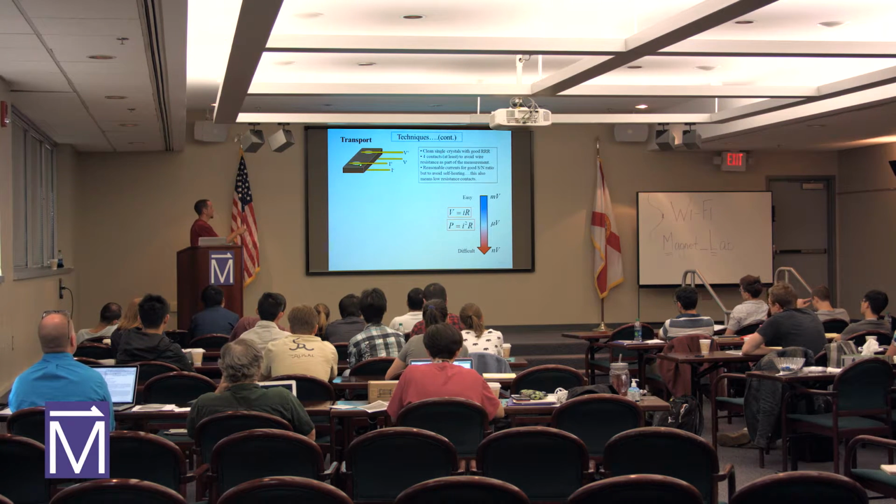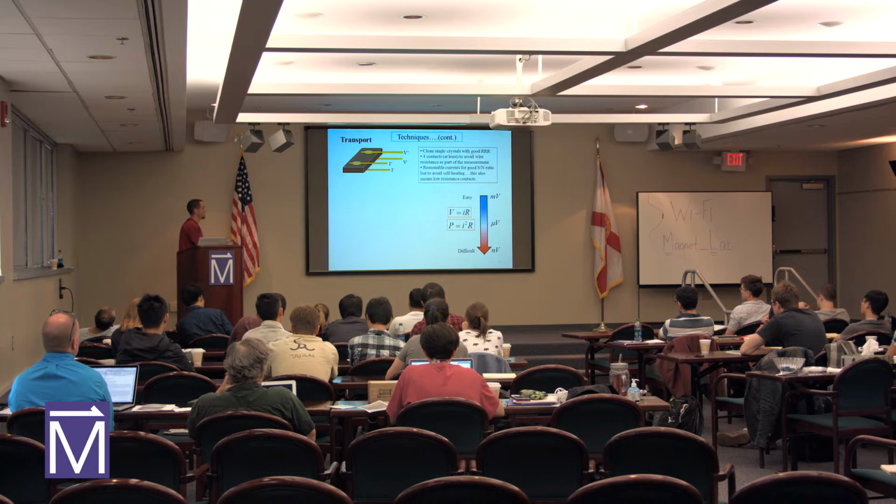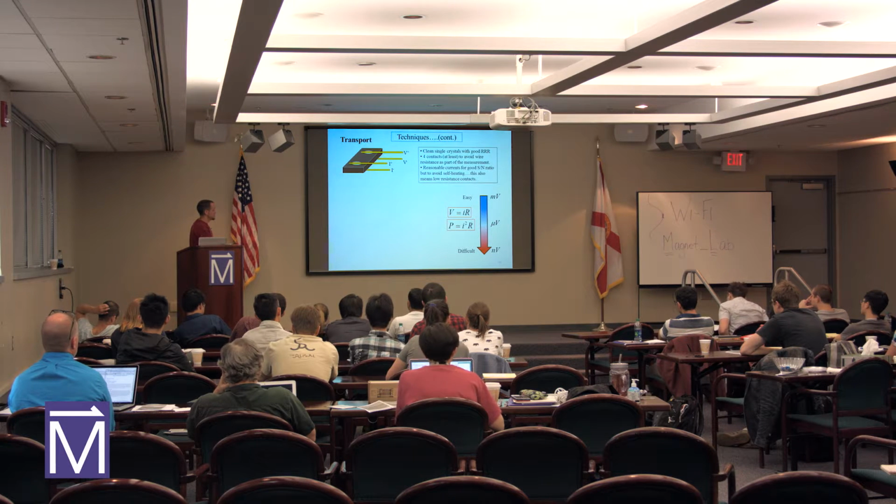If you make a contact on your sample that's a kiloohm, and you're putting a huge amount of current into it, you're self-heating the sample at its surface. It's like you've attached a little heater to it. And from experience, voltages at the millivolt level, or even microvolts, aren't that difficult to measure. The nanovolt level is nearly impossible.